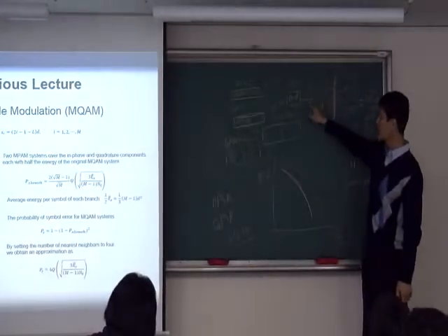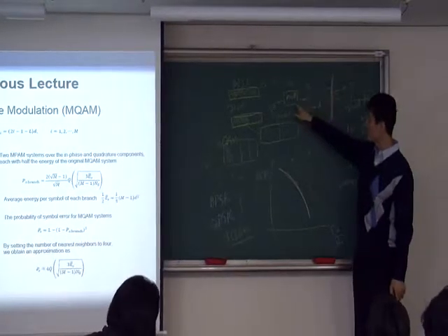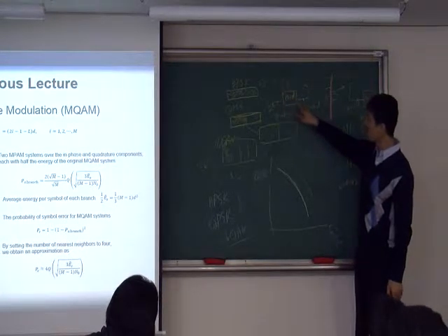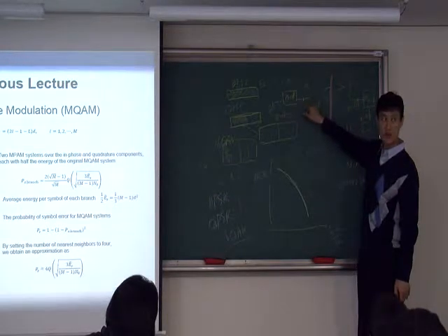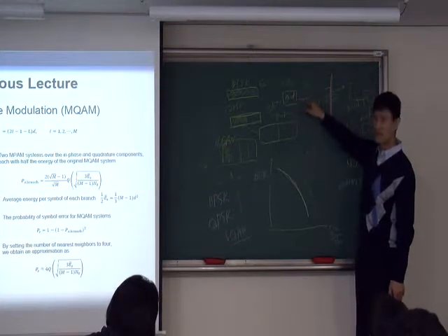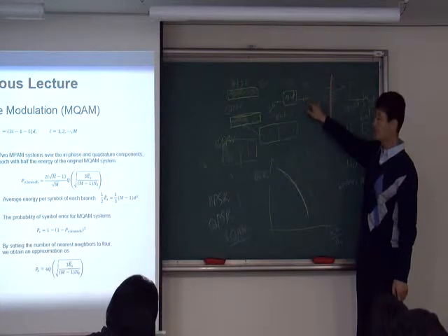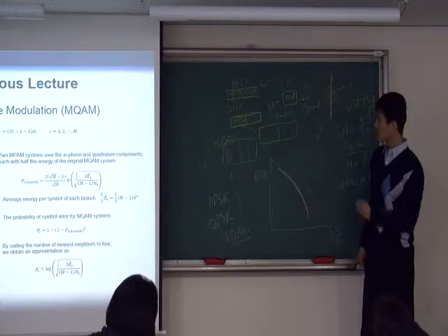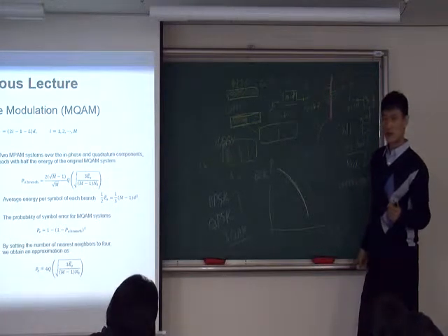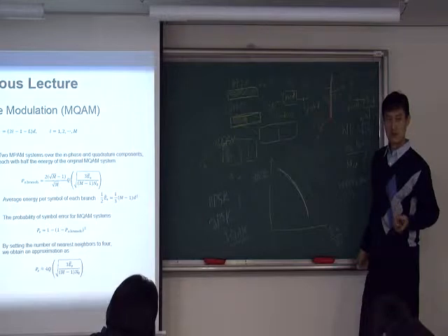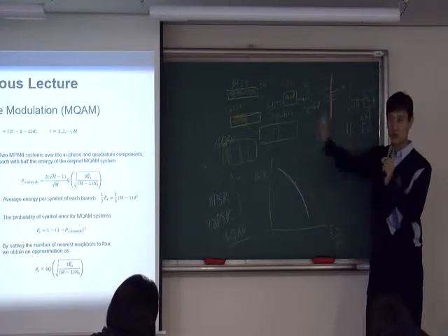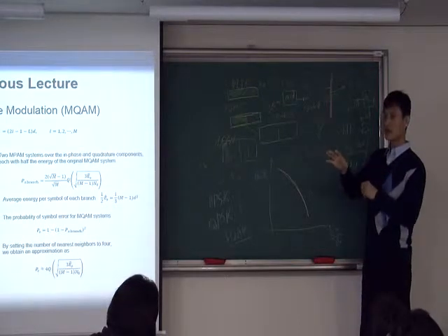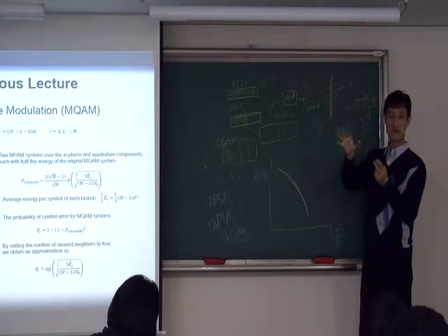But what is actually happening is that before you go through the antenna, since we are talking about baseband processing, baseband should go to the carrier, right? So when you go to the carrier, there will be RF circuits. Inside the RF circuit, there are a lot of blocks, but one of the most important is the mixer. What is a mixer? You multiply the carrier frequency in order to modulate, right? That's the mixer. And the second thing, of course, when you use the mixer, you have to have filters, right?